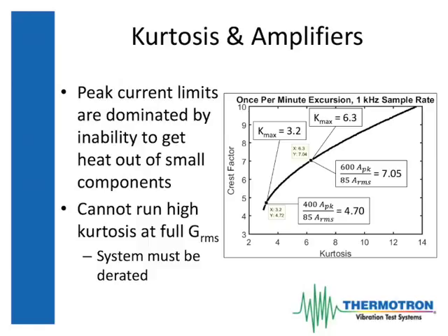And it's fairly easy, given a kurtosis algorithm, to say, what is the crest factor? So given an RMS rating, what multiple of that RMS rating am I going to see on a routine basis? And I've somewhat randomly selected the once per minute excursion. You sometimes see once per hour excursions depending on what someone's trying to optimize.